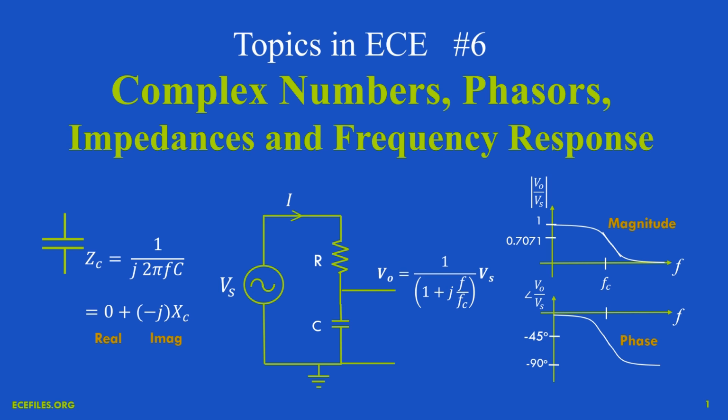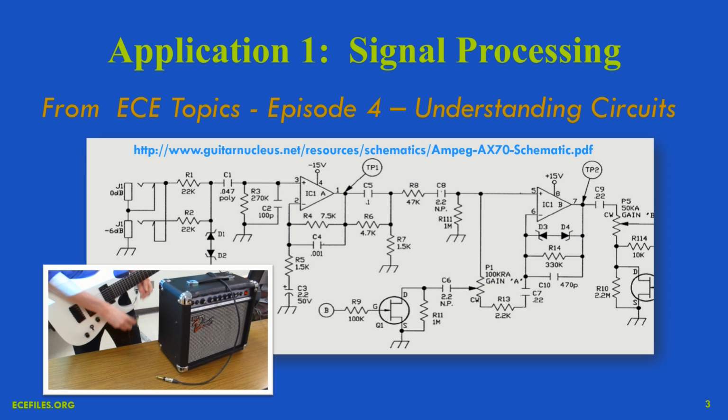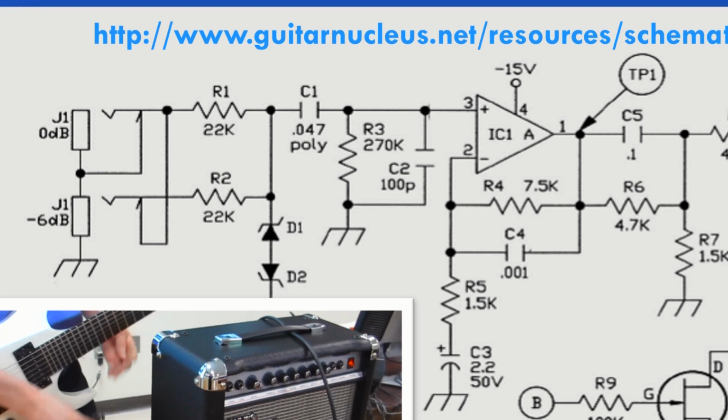Welcome to this episode on the use of complex numbers in electrical engineering. In this series, we've been learning how to look at and understand circuit schematics, in particular analog circuits such as this guitar amplifier. And we learned how to parse the schematic and figure out what each little section of it was doing. For example, C1 is blocking DC but letting the AC signals through. And C2 is shorting out high frequencies. But what does that mean?